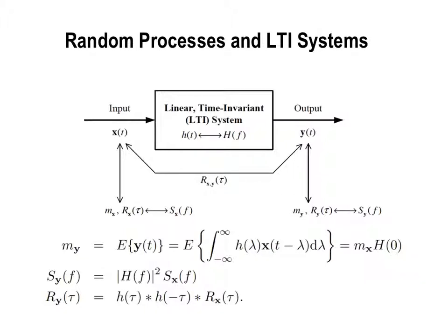So all your time representations of that random process, you will not have it represented in your first order average, the mean of the input or output. So x is the input and y is the output from this linear time invariant system, right? Again, typically if my random process is stationary, this means that this mean is a constant. We said for a stationary random process, the mean is a constant, right? If it is a constant, I just totally forgot about the existence of time variation, and the information about my random process is totally lost. I have nothing that represents the time variation of this random process, right?